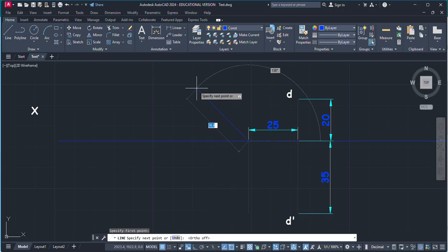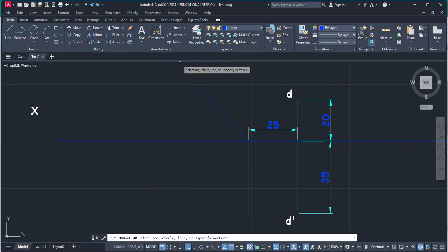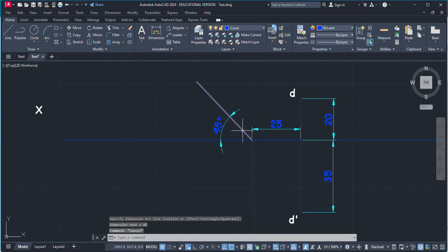Select this thing. Now the distance between this line and this XY should be 45. So from this, it should be 90 plus 45, 135. So just press shift at the rate, tab 135. Now you can check the angle between this one and this, it should be 45, so it is correct.